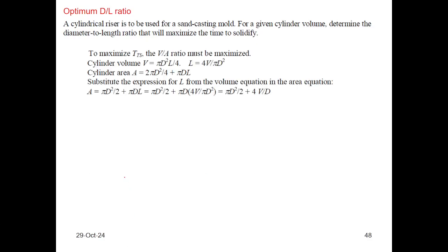It's a design problem. To maximize the solidification time, what should be the diameter of the riser? What should be the length of the riser? The volume of the riser is equal to the base area times the height. From here we can express the height of the riser as equal to that much.